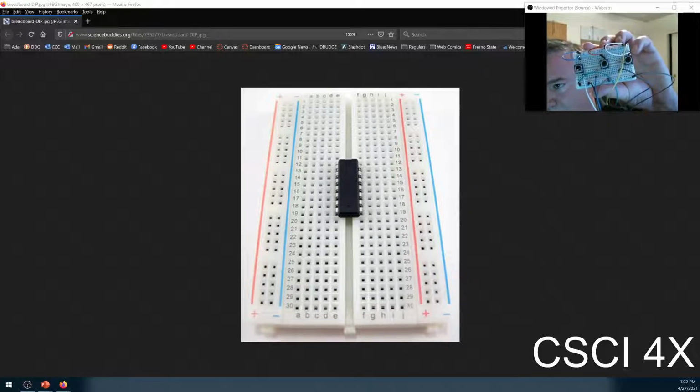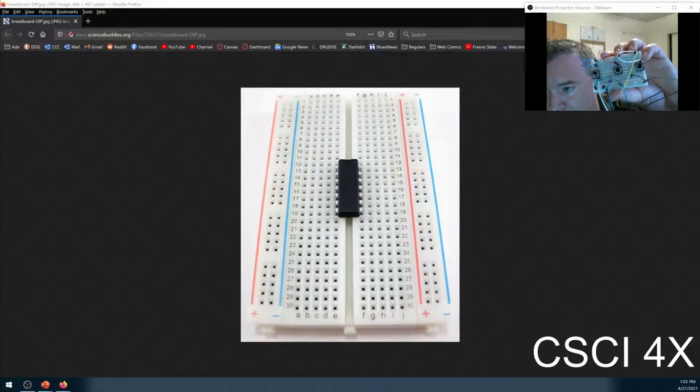So you can see it's just the same circuit repeated 3 times. Really trivial. The blue, red, and white wires are just jumping the 5 volts over from the power rail up top. The yellow wire is attached to 5 volts on the Raspberry Pi, so it supplies the red rail up top with 5 volts. Then the blue, the red, and the white just carry that over to the momentary push button switch.